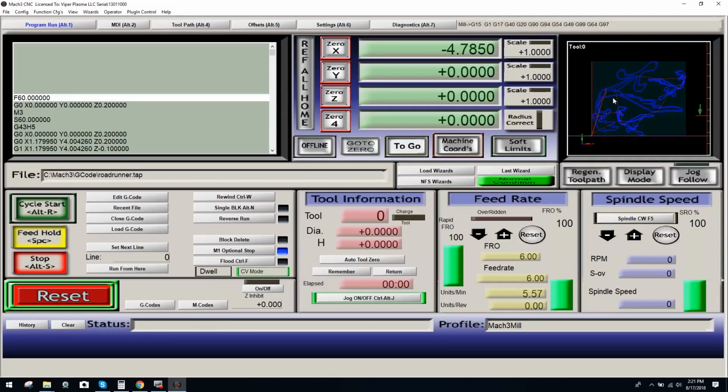You're going to do the same thing naturally, and you're going to stop 1 to 2 inches before your end stop. Once you're done, see if I can get close. Okay. Once you're done and you're ready to call that place the start position or home position, you're going to want to click your 0 for that axis. So for X, we just zeroed it out.